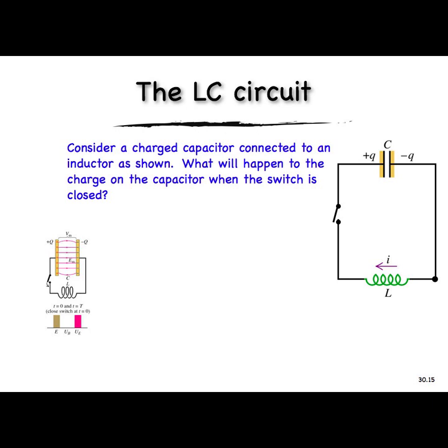I'm generating a spark. There's only a couple of volts driving this circuit. But because all I've got is basically wires and 6 ohm of resistance, a couple volts can drive a whole lot of current through this circuit.